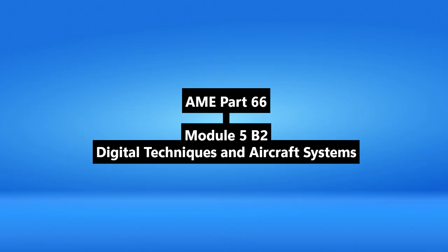Exactly. There's always a bus controller, the BC, which is the boss. It initiates all communication. Then you have up to 31 remote terminals, or RTs, which are the interfaces to the actual subsystem, like a sensor or an actuator controller. Right. And often there's a bus monitor, the BM, just listening in, recording traffic for diagnostics or analysis.